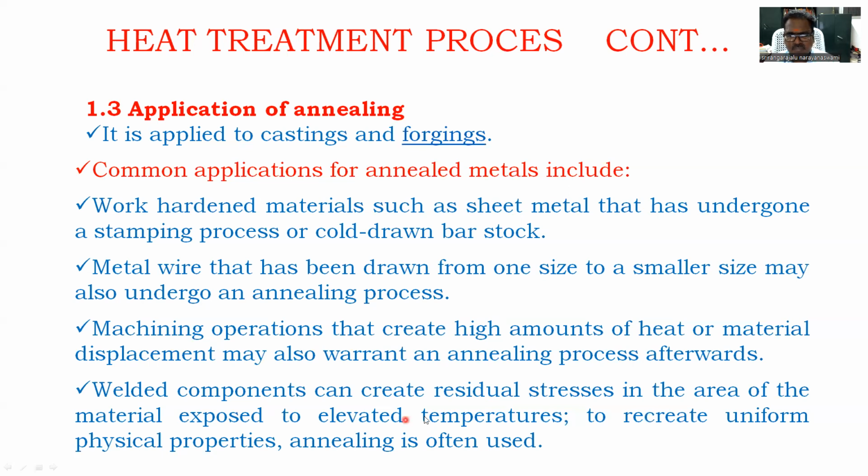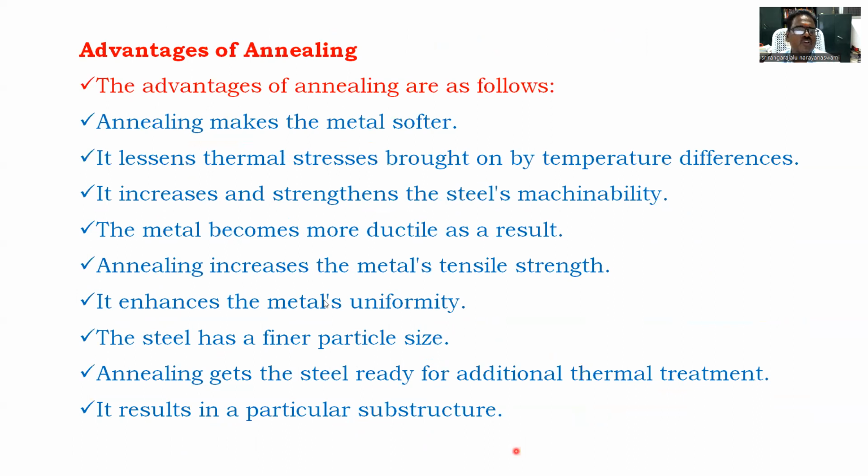Welded components can create residual stresses in the area of the material exposed to elevated temperatures. To recreate uniform physical properties, annealing is often used. So, advantages of annealing. The advantages of annealing are as follows. Annealing makes the metal softer.